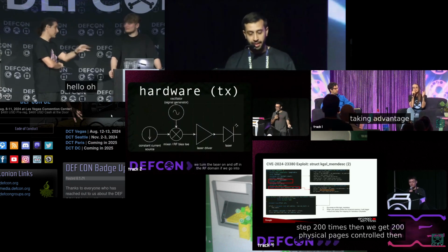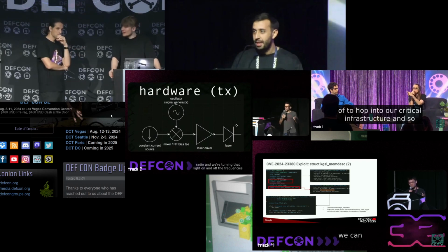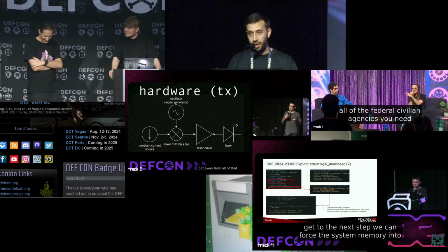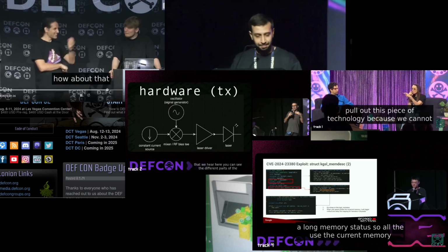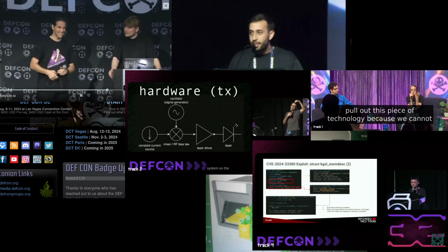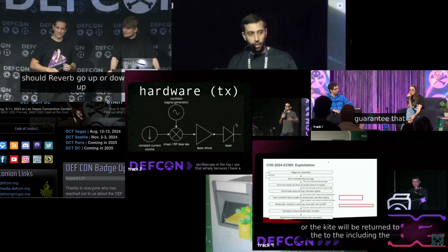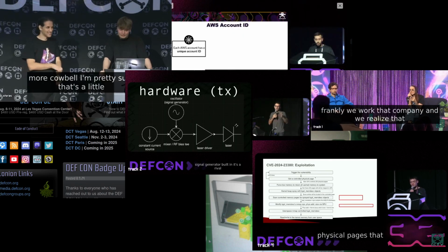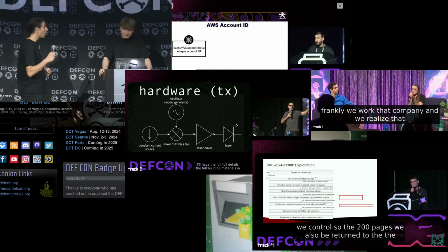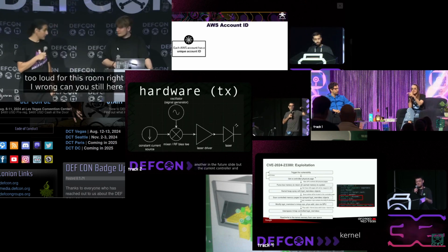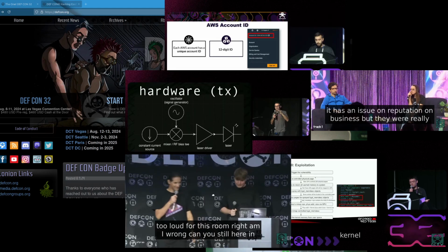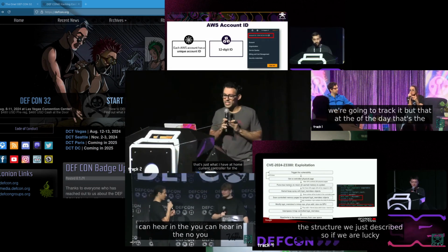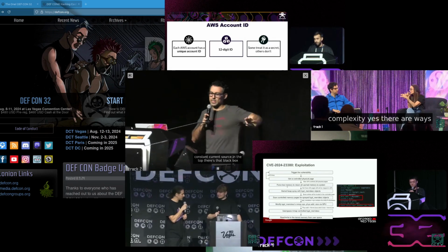So I found a laser driver. This was a laser driver I had that had something called an RF bias T. And what this means is it's a mixer. So you can have a constant current source that's powering the laser, and then you can have another source that's oscillating. And I was thinking, well, what they do in radio is that they'll oscillate things at different frequencies to get away from other frequencies that might be harming. So what if we turn the laser on and off in the RF domain? If we go into radio, and we're turning that light on and off at the radio frequencies, then we can actually get away from all that noise that we hear.